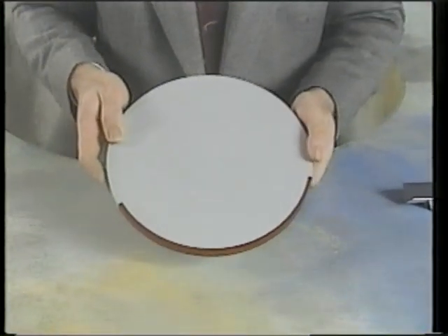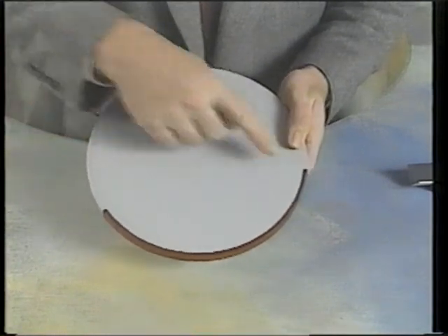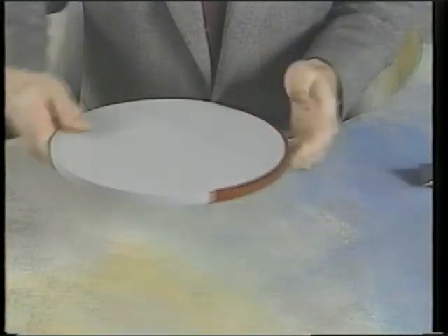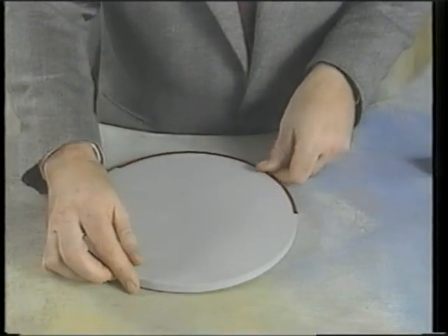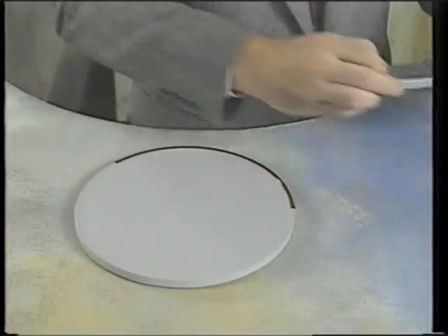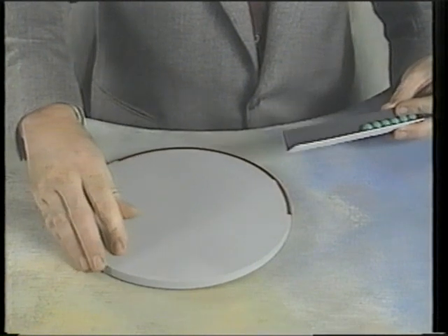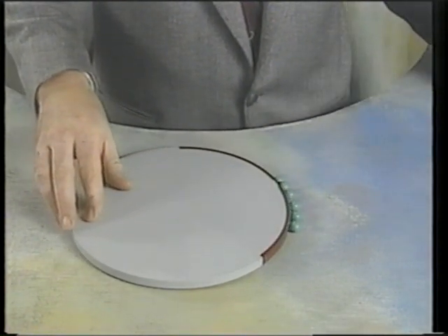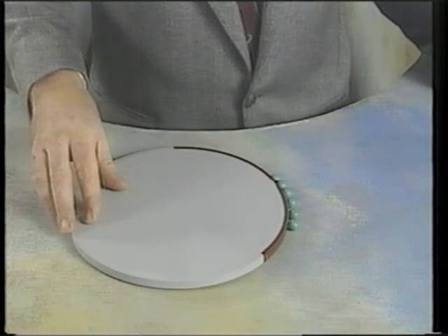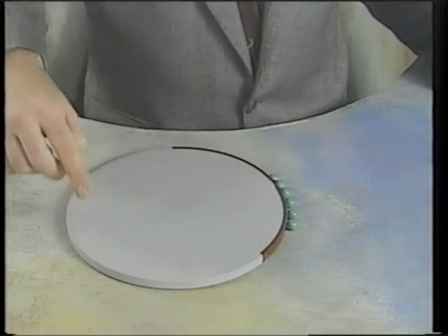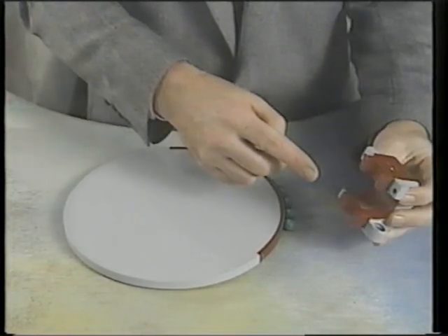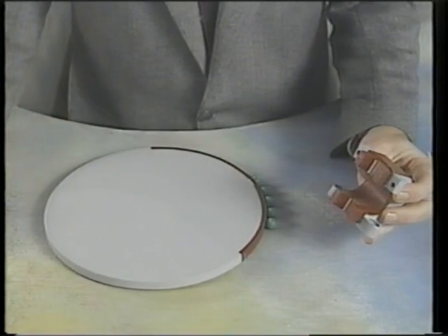Imagine this as a cross-section of a photoconductor drum, and this thin magnetic strip on the edge is the latent image. Since we're at a point after development, the latent image is coated with a layer of toner held in place by electrical attraction. These ball bearings represent the toner. After development, the drum keeps turning, and the toner on the latent image is brought near the transfer corona. You can see what's going to happen in this model.